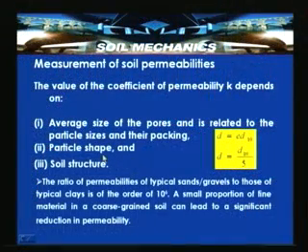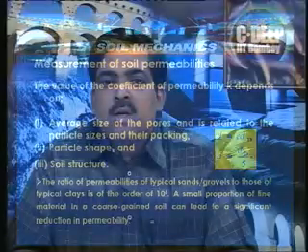And the soil structure, that is the arrangement of the particles. In case of a single grained structure for bulky particles, it can have two extremes like loose arrangement and dense arrangement, or in the case of a natural arrangement, it can be medium dense or very dense arrangement. So, depending upon the arrangement, it can have an effect on the permeability. When it comes to soil structure for fine grained soils, it all depends upon the physico-chemical environment surrounding the particles. So, that can influence the permeability value to a large extent.